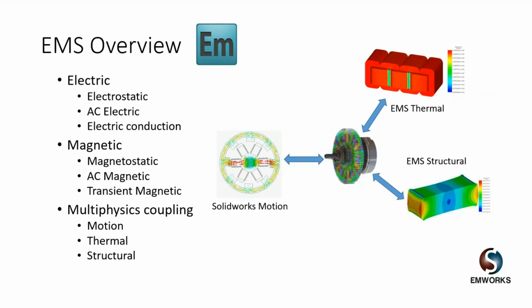And finally, if your system involves some pulse currents or some exponential currents or any kind of current waveform that you can come up with, so that the fields and losses and eddy currents are not perfectly sinusoidal, then you would have to use transient magnetic.